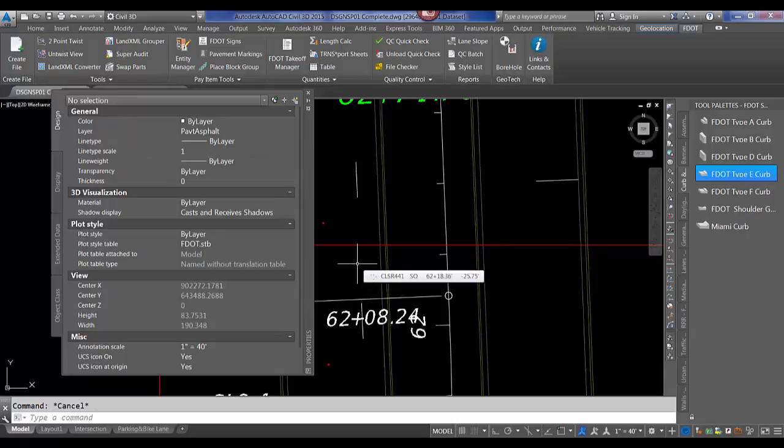And that's equivalent to, if you're used to typing it in, PEDIT, line type generation, on, off. So that's just a fancy way to get to it without having to type it in, but I still type it in. So, all right, number 6.